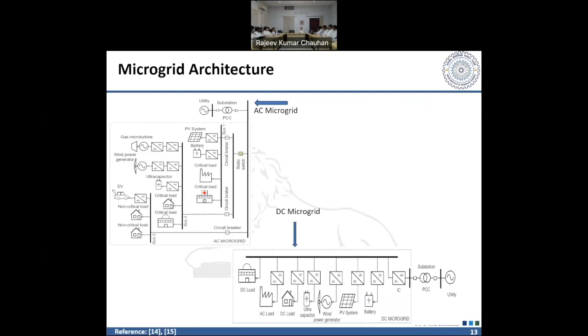Speed control हो गया AC. Induction motor. V by F control. Voltage and the frequency control. So by this, if I can make my frequency variable, I can control V by F.